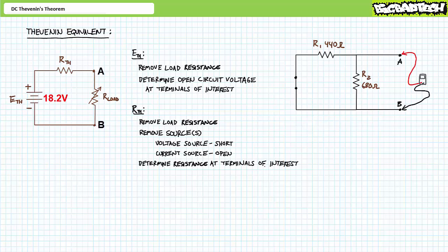If you want to, you can draw a little ohm meter on the terminals of interest, reminding you that perspective has shifted. The removal of the source and perspective shift changes the game, and a lot of people unnecessarily freak out about this. Chill out, relax, visualize the circuit at the nodal level and from the perspective of flowing current. In this circuit, an ohm meter reading the resistance from A to B would see R1 clearly in parallel with R2. This is fundamentally different than the relationship we previously observed when calculating the open circuit voltage ETH and during the original series parallel circuit.